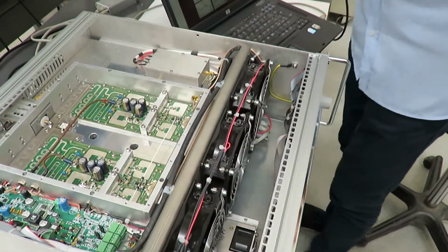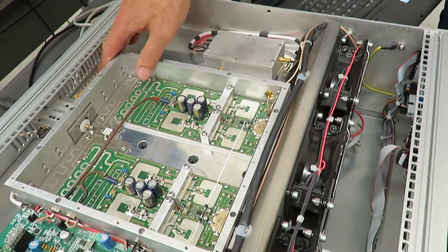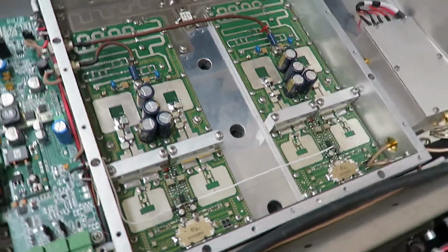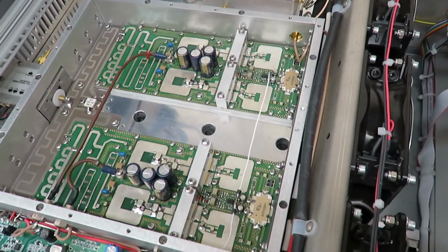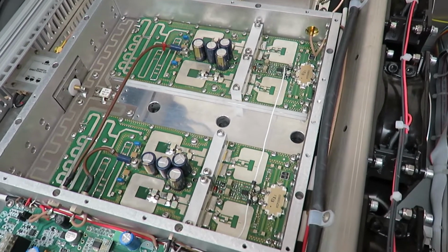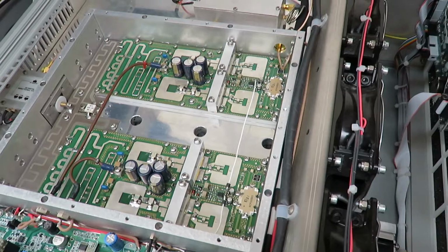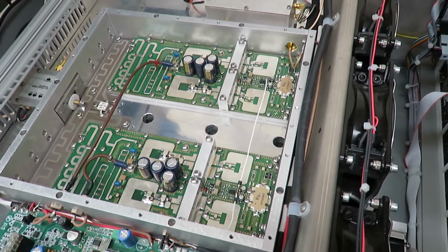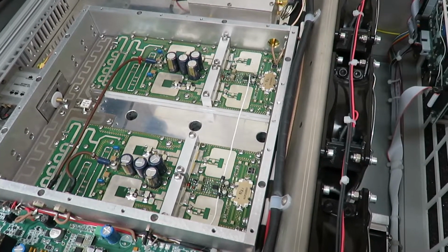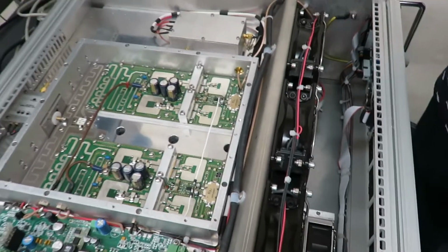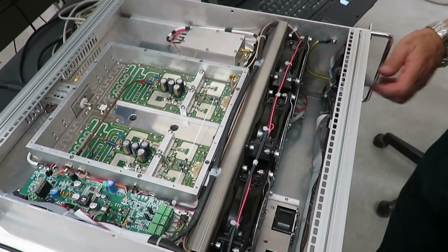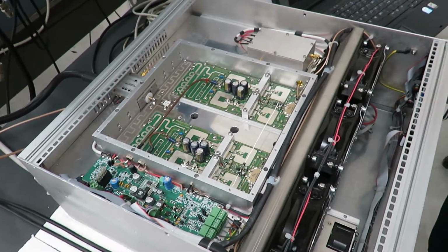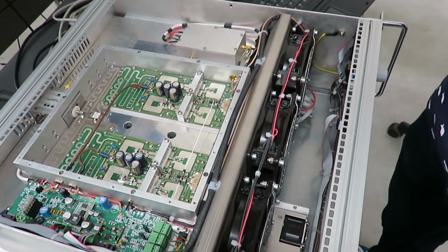Okay. Now, let's say this is the amplifier? Yeah. The secret of Doherty technology is just here. The 500 watt amplifier is made by two RF amplifiers. Each of them is 250 watt RMS. And there is a big difference to legacy push-pull class AB amplifiers. Those, until now, were made by the so-called push-pull technology. So a couple of RF devices, one amplifying the negative section of the signal and the other the positive one.